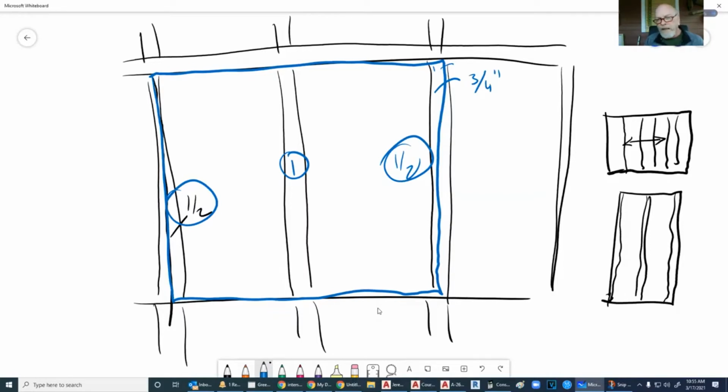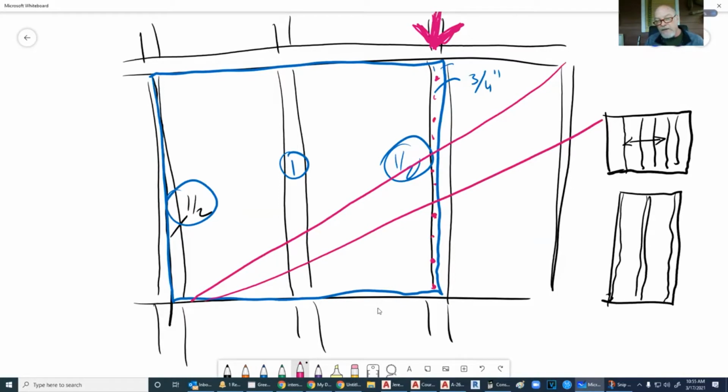So anyway, getting this dead on center in advanced framing is super critical. And by going down through here and putting a nail at that 3/4 inch space right there, you don't have a whole lot holding on. So if you've got a lot of downward pressure on here, a force, let's say for instance, God forbid that it was a 2-story or 3-story house on this type of framing, then this is super critical here. And wherever these joints are, we would need to have some sort of diagonal in here to keep this from pulling out, because I'll tell you what, if you've ever nailed plywood